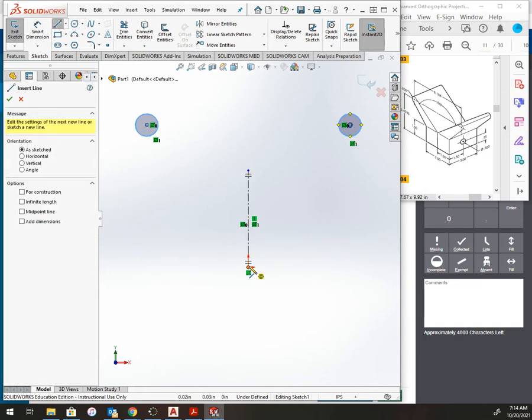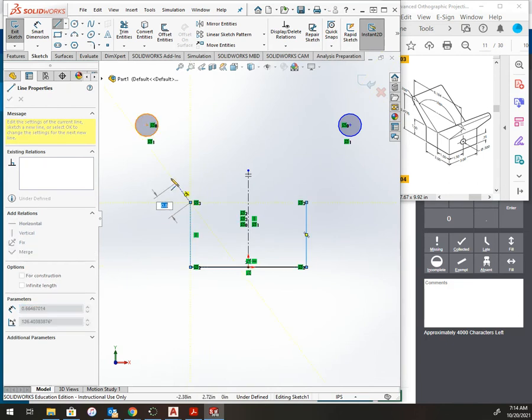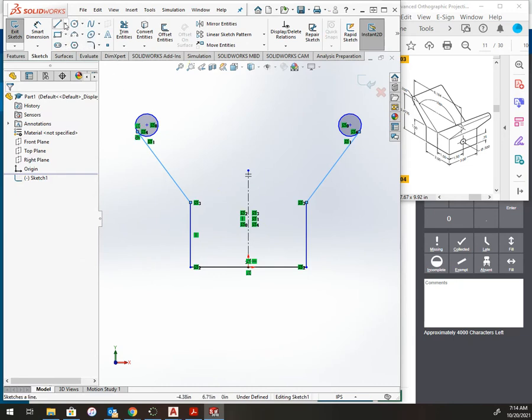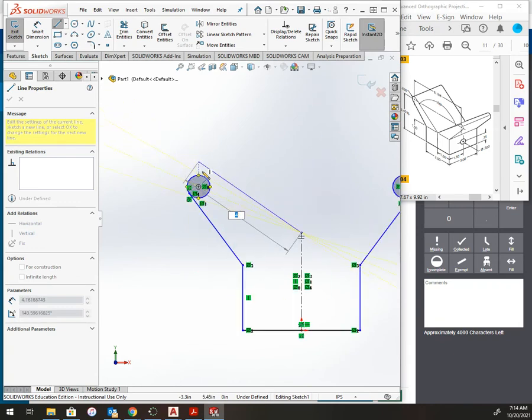So now I'm using the line tool, and I'm going to draw over. I'm ignoring the measurements on here. This next part, which is where we had difficulty, make sure that you snap when you see a coincident and a tangent snap forming. Reselect the line tool. Now I'm going from this point here over to the circle. Again, I'm looking for tangent and coincident.